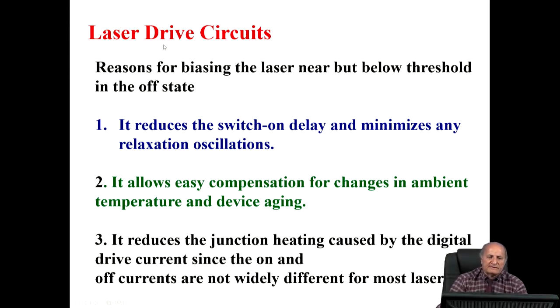When we use a laser in digital modulation, we must keep the laser bias near threshold at the off state, so the laser is ready to be on when logic 1 comes.